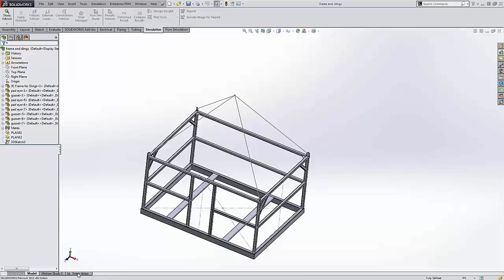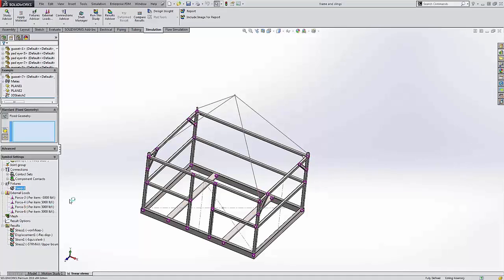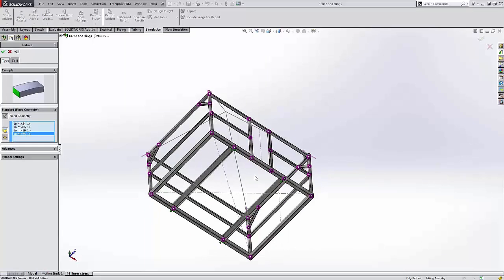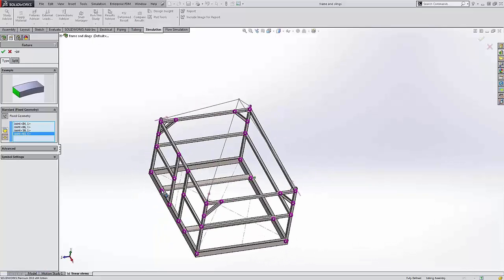Let's start with that restraint. Wherever the equipment is, that now becomes a restraint. In this case, these two rectangular channels, or C-channels, are what the equipment's loaded on. So I'm going to restrain the 4 joints.